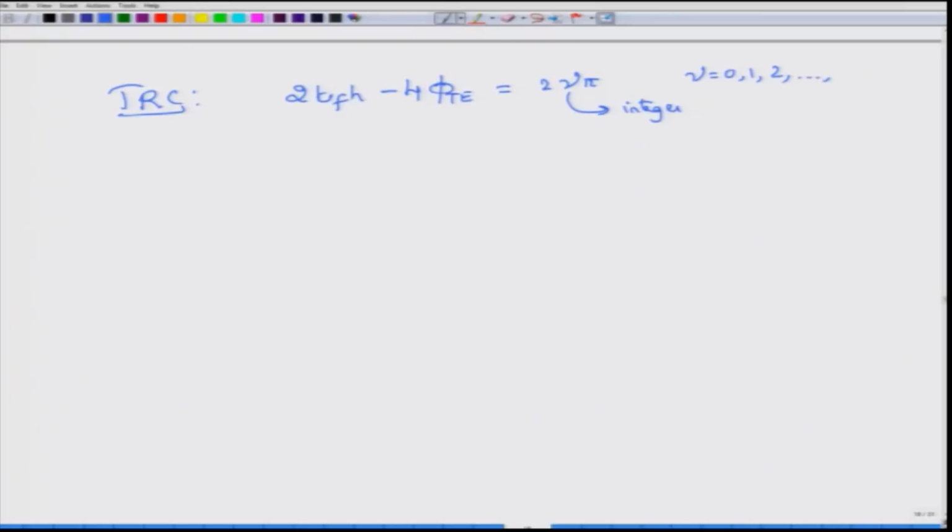Each value of nu satisfies a condition and then gives a different value of incidence angle theta 1. So, it will not be a continuous value of theta 1 from right at the critical angle all the way up to pi by 2. Not all these angles, light launched at these angles will be guided by the waveguide.